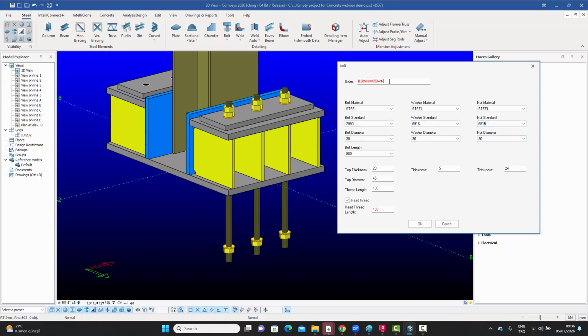And then we have given you a format with which you actually define the location of the nuts and the washers and everything. So B means bolt, N means nut, and W means washer. With this coding, any number which you put in basically is a gap. So when I say B20, it means there's a bolt, then there's a gap of 20 millimeters, and then there's two nuts after that, as you can see, and then there's a washer, and then there's a gap of 650 millimeters after that, and then there's another washer, and then there's a nut.